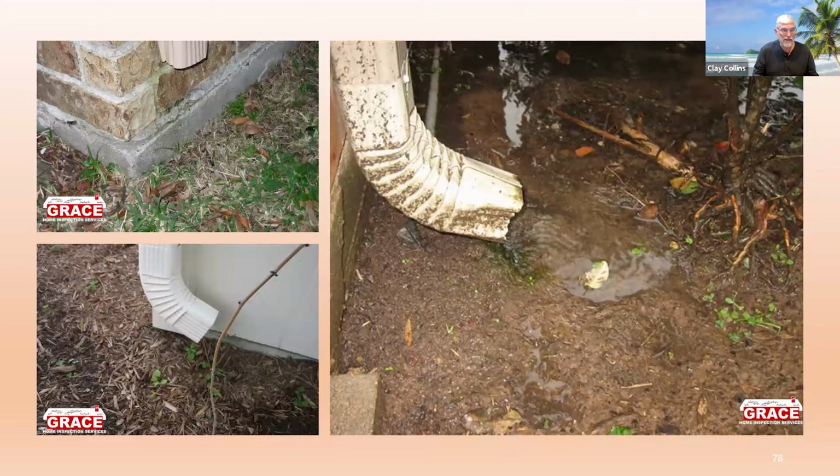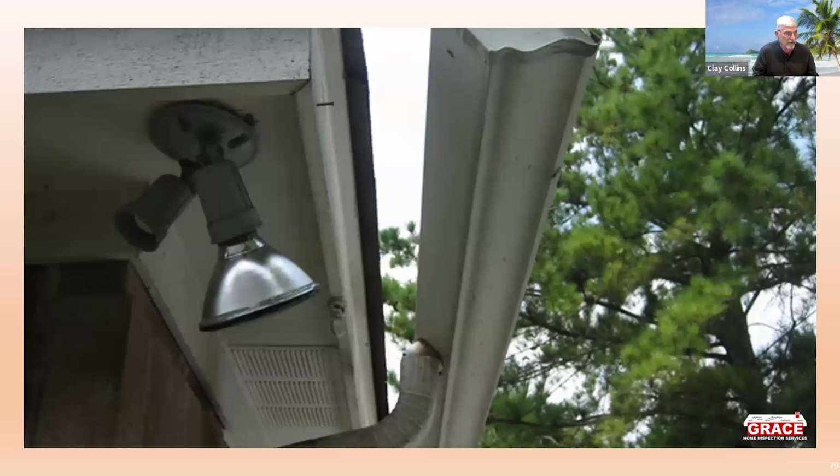And if you don't take care of your gutter, it's not going to take care of you. You can see that basically the nails failed. And that is a deficiency in the gutter. It is a failure of the gutter system and would have to be reported. So what about if a nail has begun to pull out?